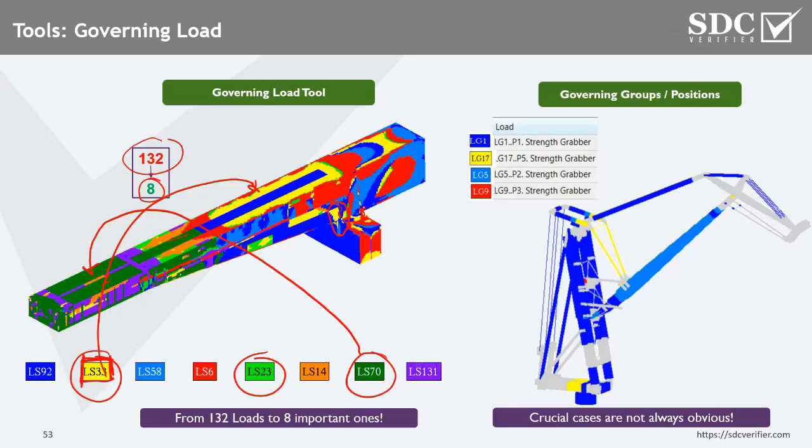Same thing is related, for example, to jeep crane. Yeah, so you see that, okay, this yellow short braces and here the platform, the highest stress level is coming from extreme position number 5. While for the front arm, position 2 is the most important, not even 1 or 5. So this is an intermediate position. So this is very useful to know.